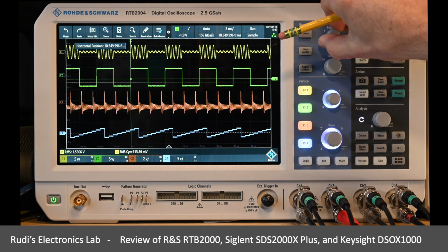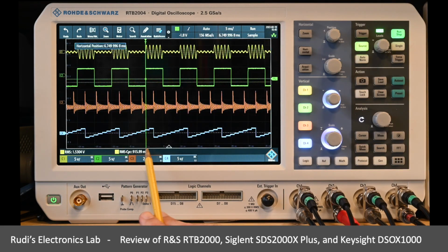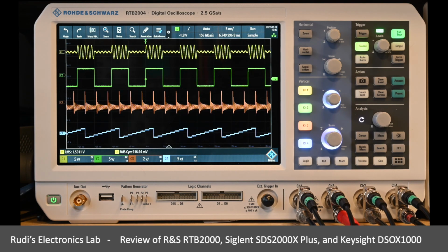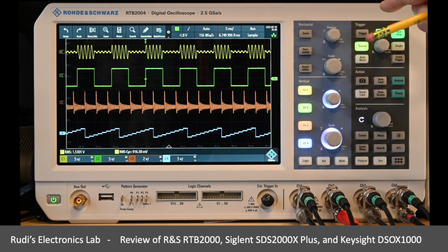And if I go to a low area here on the back, no, it's still at 0.9. So this isn't doing what the manual says that this function is doing, I think. I tried to dig into that a little bit, and I think I came a little bit closer to what the oscilloscope is actually doing. And to demonstrate that, that's why I have the ARP function over here. I could also have used the ramp, but in this case I use the ARP function.